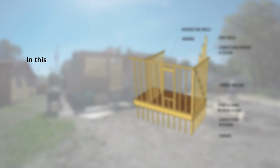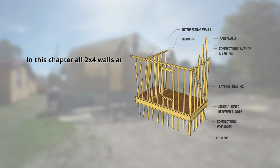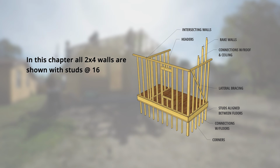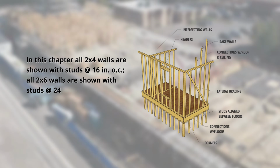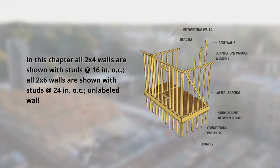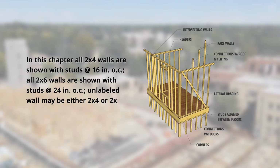Framing. In this chapter, all 2x4 walls are shown with studs at 16 inches on center. All 2x6 walls are shown with studs at 24 inches on center. An unlabeled wall may be either 2x4 or 2x6. Take a look at this detailed illustration.